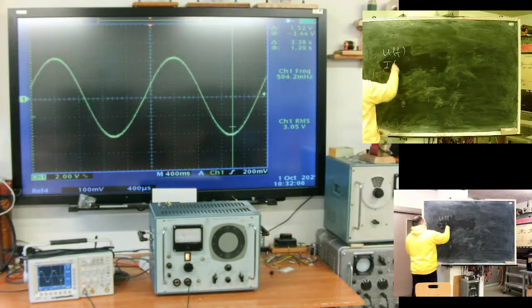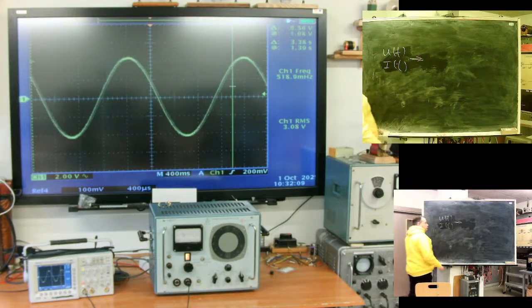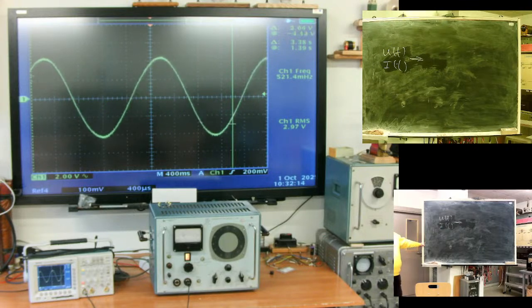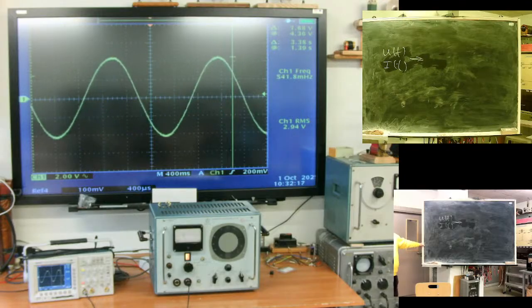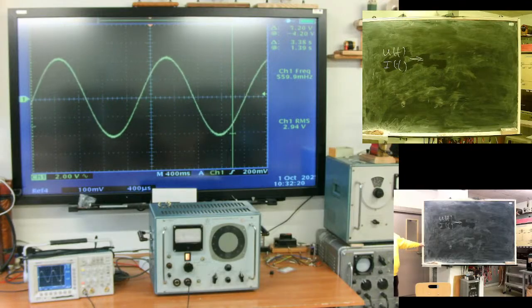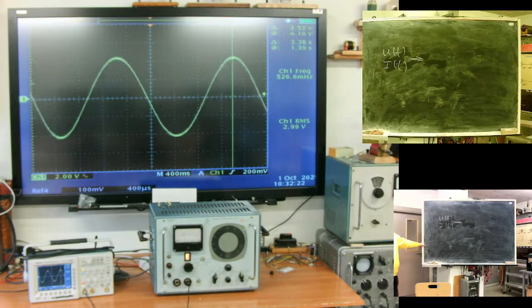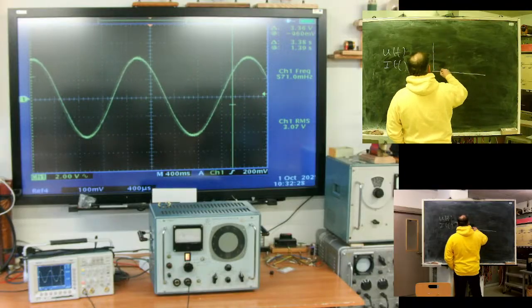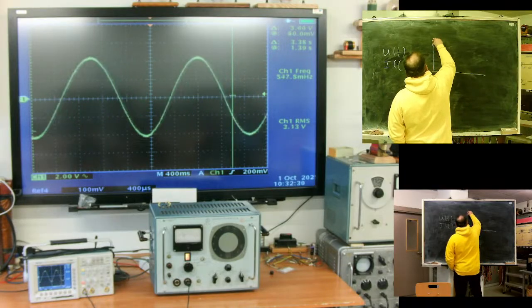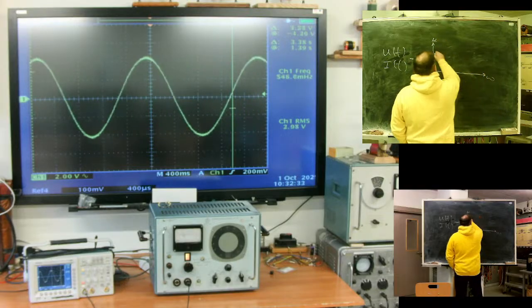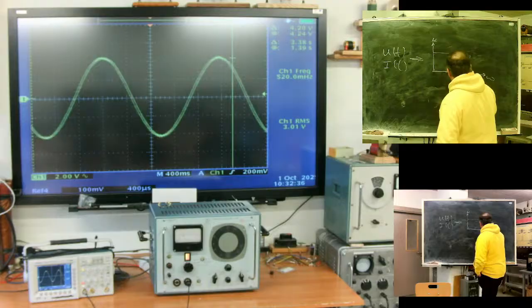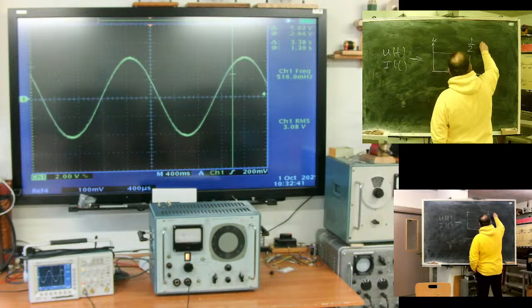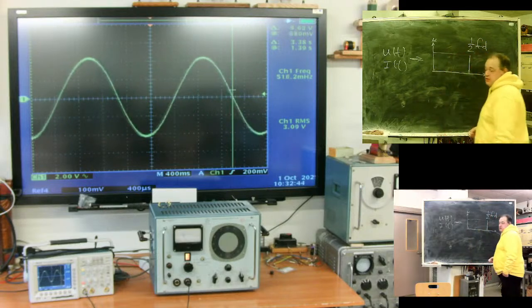You have voltage, you have current at the input. At some point you need to do one thing. You have a device with limited calculus capability, a device with limited sampling rate. You need to limit the spectrum of your signals. Here is the borderline. It's one half of the sampling frequency of your device.